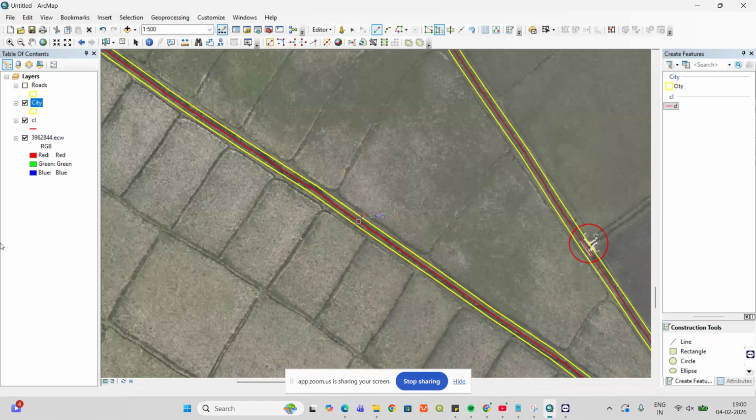As we know, in slopes and all, there are possibilities that in the area coverage, from the top view, you will only see one side of the building. So to avoid that case, we are flying at very low altitude with the terrain sensor to even out the altitude of the drone with respect to the ground level, not the mean sea level. What we usually do on plain terrains is match it with the mean sea level. Like 60 meters means it will fly 60 meters above mean sea level, not the existing ground level.